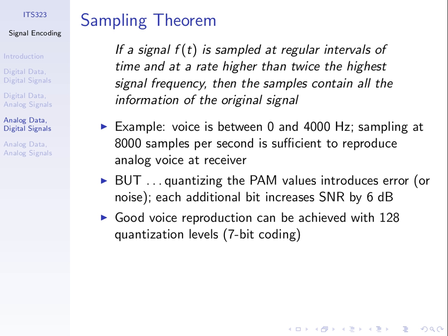So it depends upon what the audio input is as to what a good number of levels is. It turns out with voice, people have done tests and found that using 7-bit coding, that is 128 levels or 128 code numbers, is usually sufficient to give good quality voice reproduction. That is, if you play back some voice recorded with a sampling rate of 8,000 hertz and 128 levels, then what your ears will hear will be almost a perfect reproduction, or a sufficient reproduction, of what the original voice was. With music, it's different. As we've seen in this example, music has higher frequency components, therefore we need a higher sampling rate. And we normally need more bits to reproduce it, because we normally want music to be a higher quality than voice. So we use more bits, say 32,000 levels in this case. So it depends upon what the analog input is as to what is the optimal number of levels.